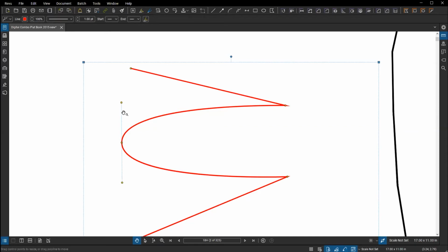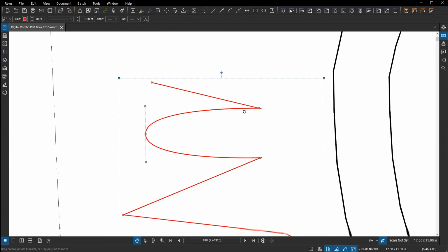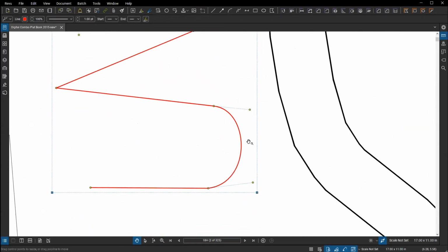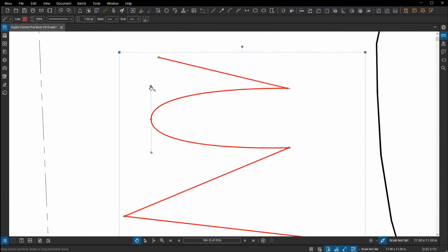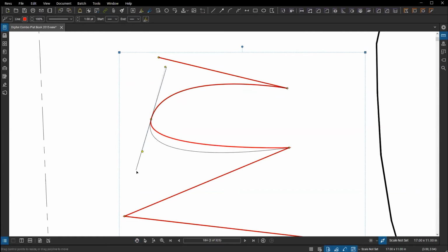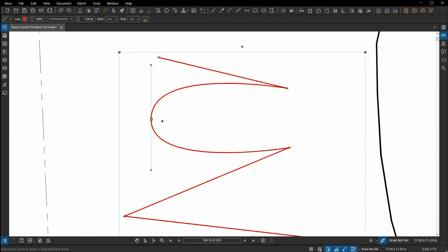Now my control here is a little bit different from what I had down below, where there was a handle on either end where it attaches to the next line segment. This is now one handle that passes through that control point. So as I twist it, or lengthen it on one side versus the other, I have control over the shape, size, and angle of that path being used. And you can still always manipulate the placement of the individual control points it passes through.